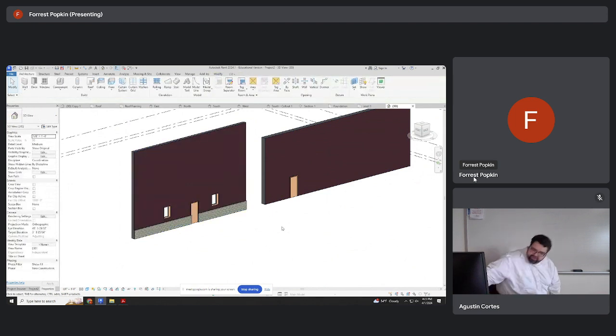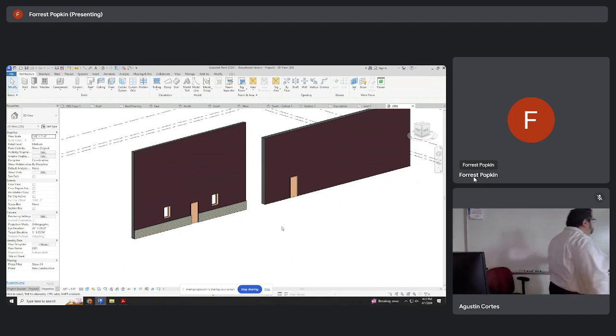Well, in Revit, what they're saying is, I have wall type A, and if I mix that with wall type B, and I'm putting them in some ratio on top of one another, you could call that a stacked wall. This is basic. And I push those together, and I get a so-called stacked wall.